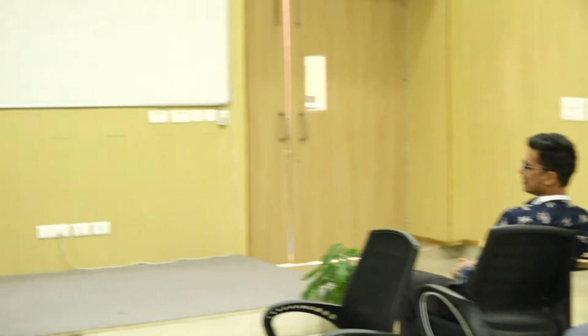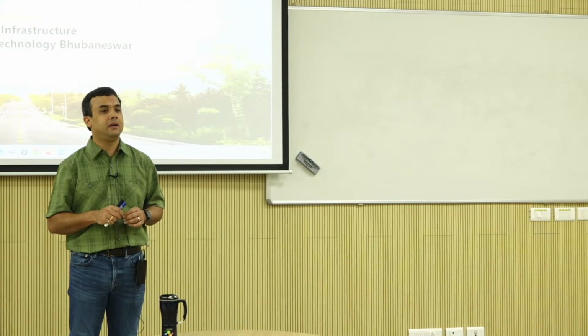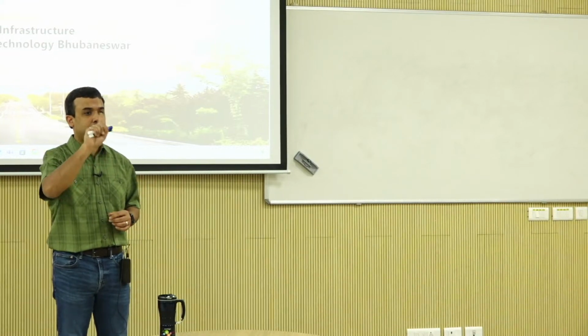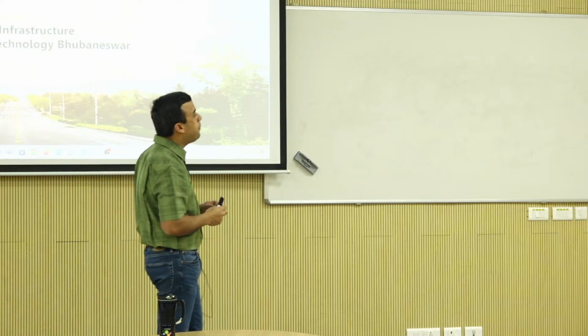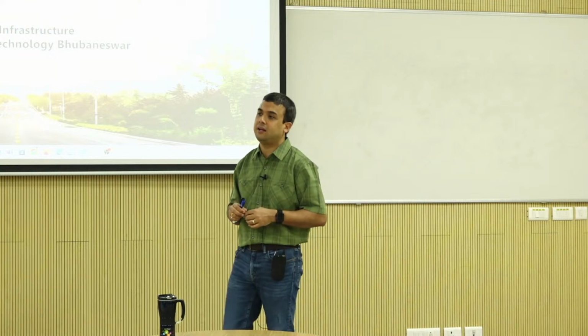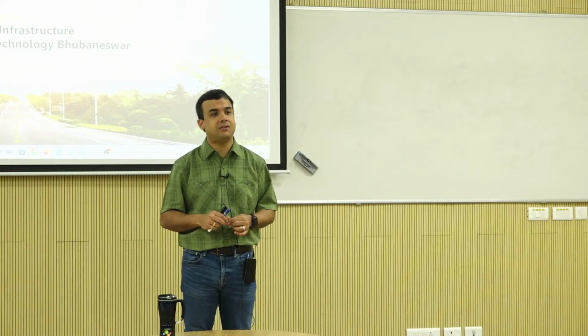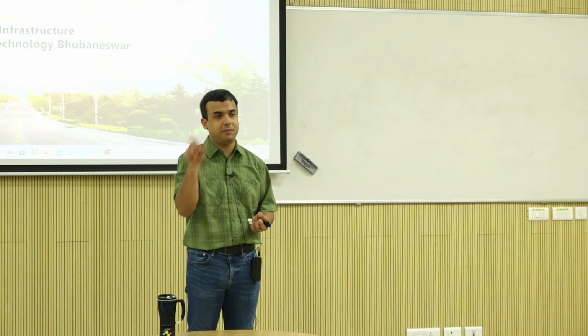Go ahead. So modulus. All I can say is I have done FWD work on cold in place recycling, cold mixes, and some modeling. I have not tested them for resilient modulus, but the modulus we used was 100,000 psi. If you want just one E value, it's about 100. A typical good quality aggregate was about 40. As I showed, 40, 45 is a very good quality aggregate. We used about 80 to 100. That's all I can say. I've not tested it myself, but that's the FWD.